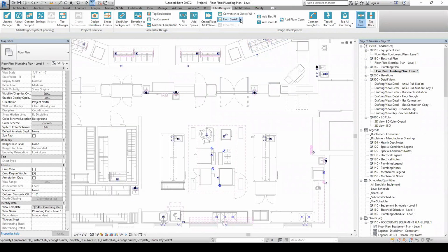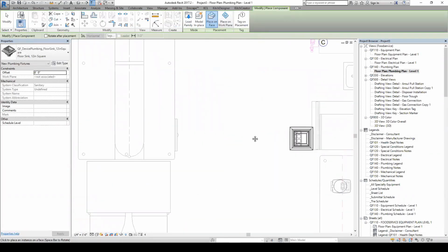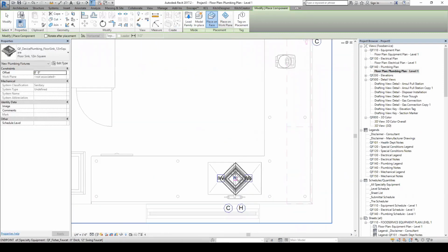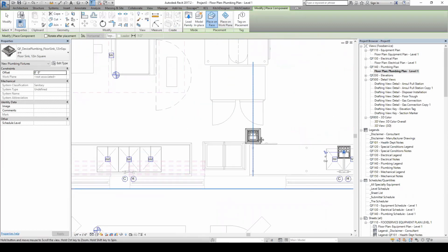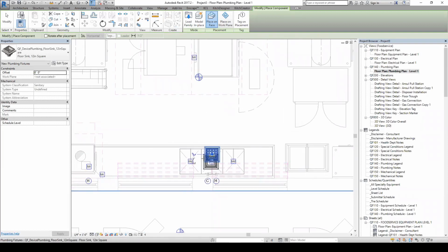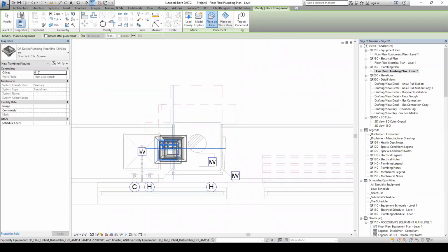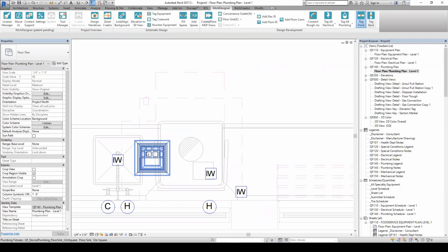For plumbing, we would go and we would place our floor sinks. You can have the add plumbing Roughin button place floor sinks for you. The only thing is, you could set it up to place a floor sink whenever indirect waste is greater than 0, and just place the floor sink in the center of the family. The thing is, it's just going to take a lot of tweaking. As you guys know, we use less floor sinks than we have indirect waste connections. So I could use this one floor sink here and I could catch the soiled sink and the dishwasher.